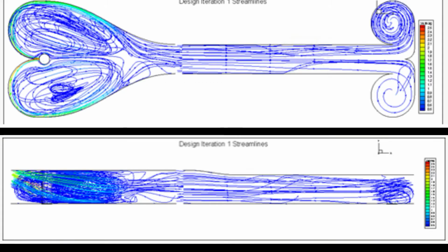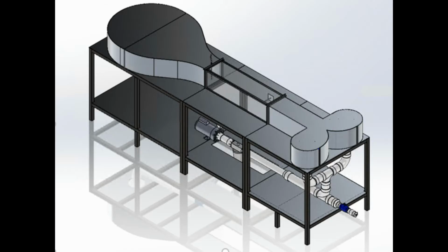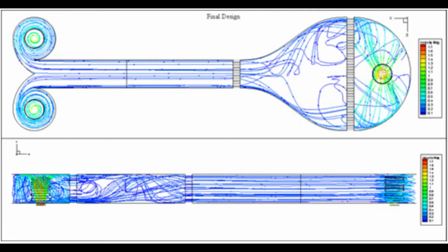Computational fluid dynamics analysis was completed on the tunnel section of the design. Extensive analysis shows improvements in flow as a result of design changes such as different tunnel shape, an additional flow guide, and cone-shaped inlet pipes. As a result, the chaotic flow of the initial design is, while still not perfect, drastically improved, producing a much more uniform flow in the test section.